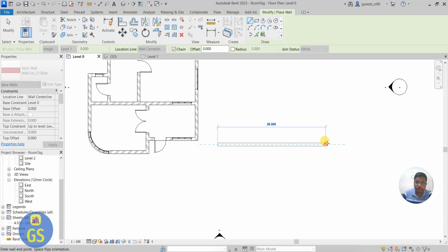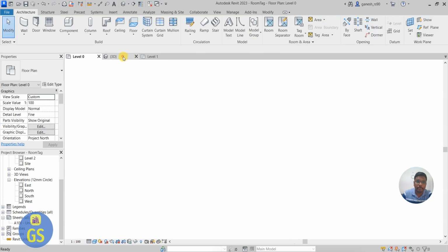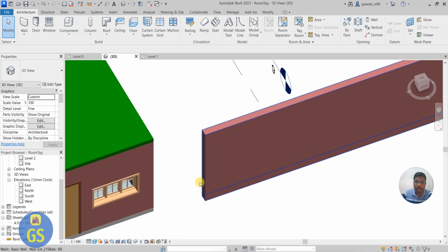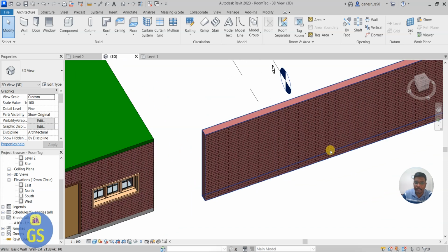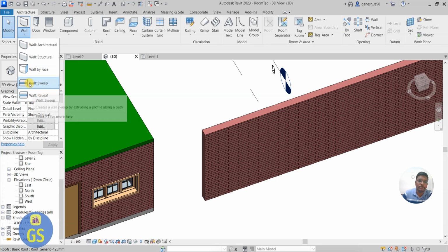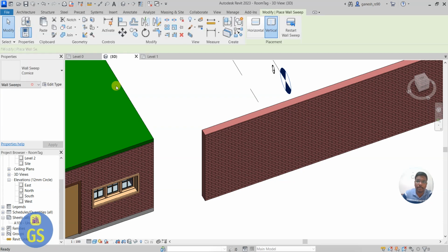You can go for a small wall. Now in this wall you want to take some horizontal groove. A groove is some kind of horizontal groove you want to take in a part, or a vertical groove, that is a small cutting you want to make in the wall. In such a way we can go for sweep or reveal. See the sweep, how it is going to work. Horizontal sweep you need, or vertical sweep. When you select this vertical sweep, you can see this thickness.